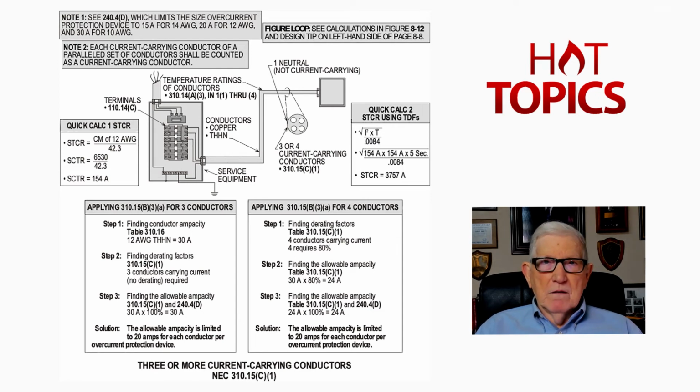Now, we know from our experience a circuit breaker at 600 volts or less will hold about 3 times its rating. So if you had a 30 amp circuit breaker, it'll hold 3 times 30, 90 amps, and it'll hold it for, well, it depends on the voltage. If you were 120, 240, or 208, it'll hold for about 9 seconds. If you're 480, 277, approximately 4 to 5 seconds.